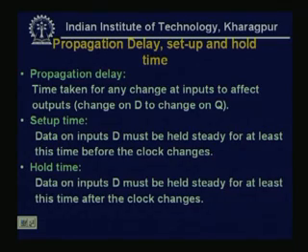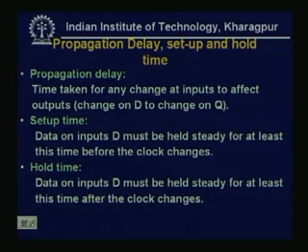Now, setup time. The data on input D must be held steady for at least some time before the clock changes, so that we can get the fault-free output. This time before the clock changes, for which the input must be kept steady at the input line, is called the setup time.